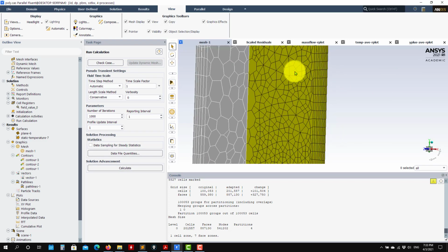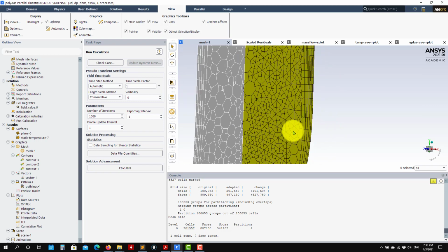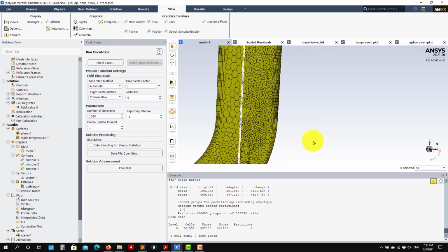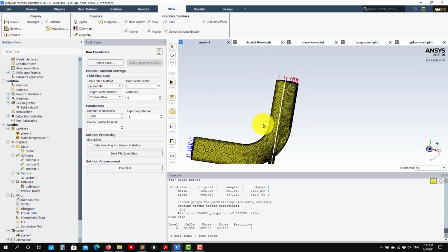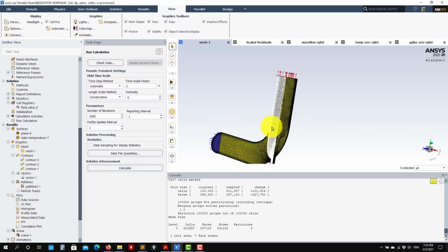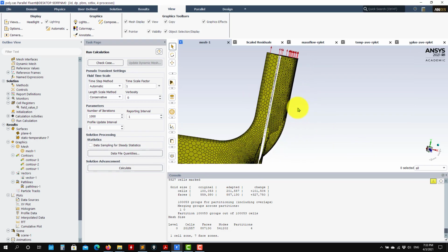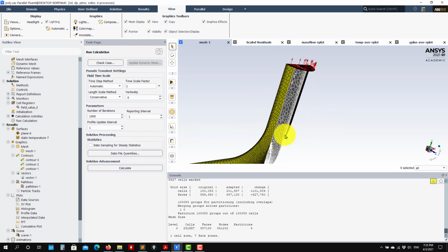But here I think you also got the idea, see also that it affected the boundary layer, that your mesh can grow really fast, the cell count. In 2D it wasn't that big, but in 3D you start to see that this will grow really fast. So this is something that, my advice again, do not abuse it.